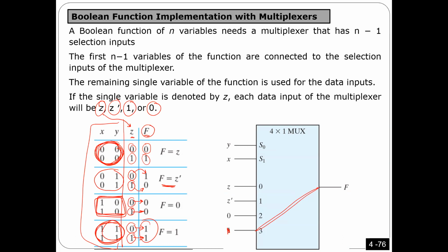Okay, guys, I'm gonna say again what I did. I already accepted the naive idea. The naive idea is that the number of inputs in the multiplexer equals the number of entries we have here. But I can use a smaller multiplexer, and that's what I did. You have 8 cases, but I use a 4 times 1 multiplexer, as you see here.